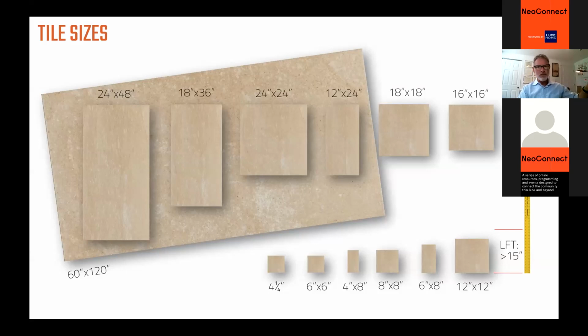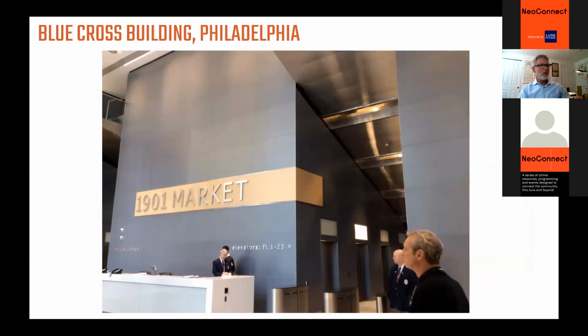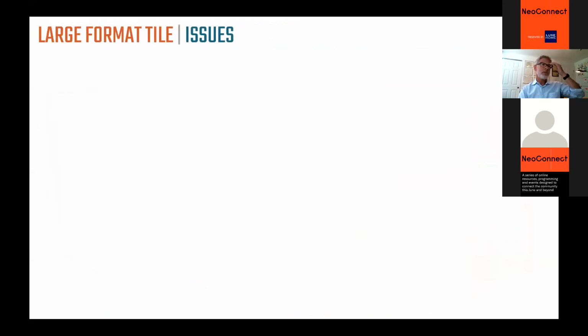That would be a different category, called gauged porcelain tile, and we'll get into that in a minute. Here's an example of this ultra large format gauged porcelain tile in use in a lobby. If you want that really clean look, the super large format with very few grout joints, so it's low maintenance and really contemporary, gauged porcelain tile panels is what you might want to specify.